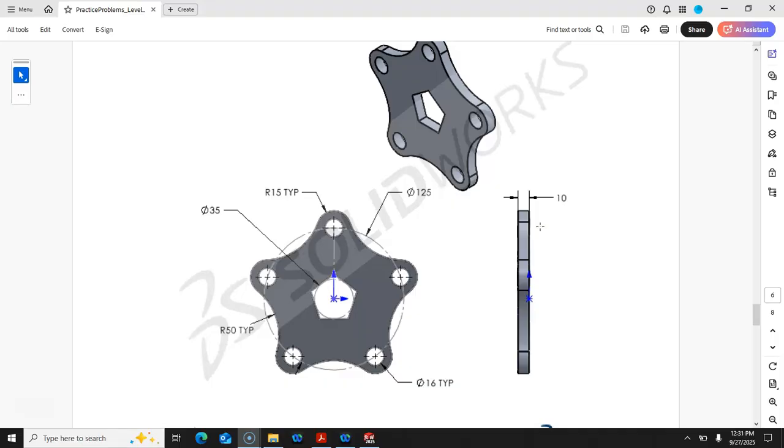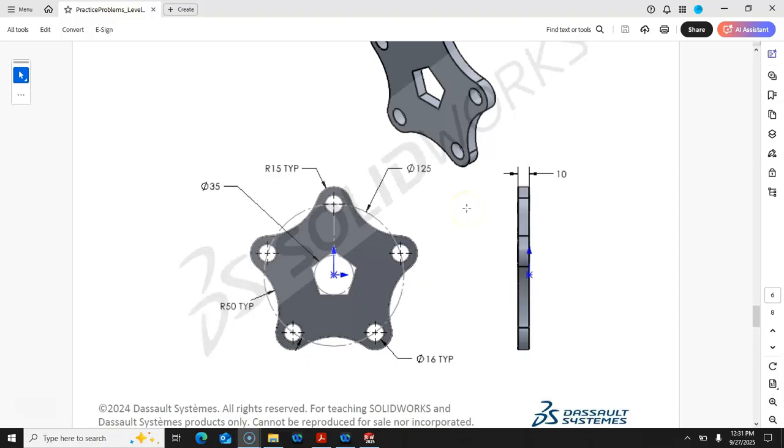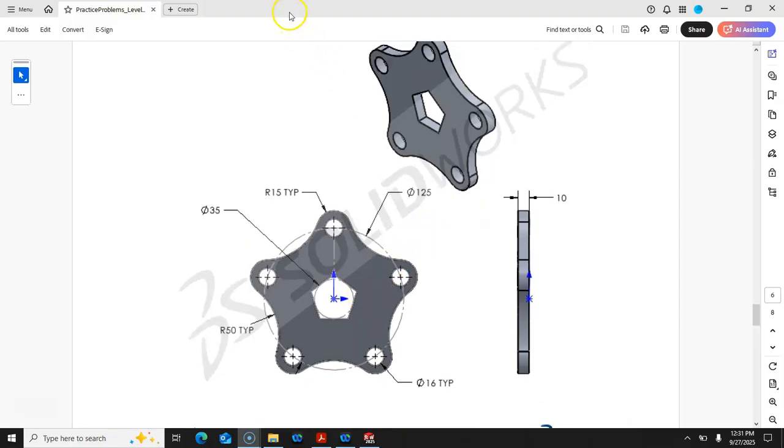I like this geometry. When looking at this, break it into its component pieces. If we generate the base circle, the circle, and one segment of the arc going into the tangent arc, and then pattern that around, we can connect the endpoints and see what that gives us. Previously, we did the lace gasket that had 12 or so arcs on it, which was a little more complicated. So this one has some interesting geometry. Then we'll go back to the polygon and get that